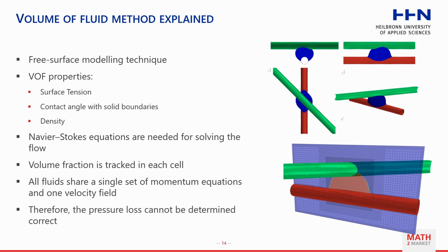But it is not a standalone flow-solving algorithm. The Navier-Stokes equations describing the motion of the flow have to be solved separately. While the volume fraction is tracked at each cell, all fluids share a single set of momentum equations and one velocity field. Therefore, the pressure loss cannot be determined correctly in the volume of fluid simulation. Only the shape and behavior of the phases.